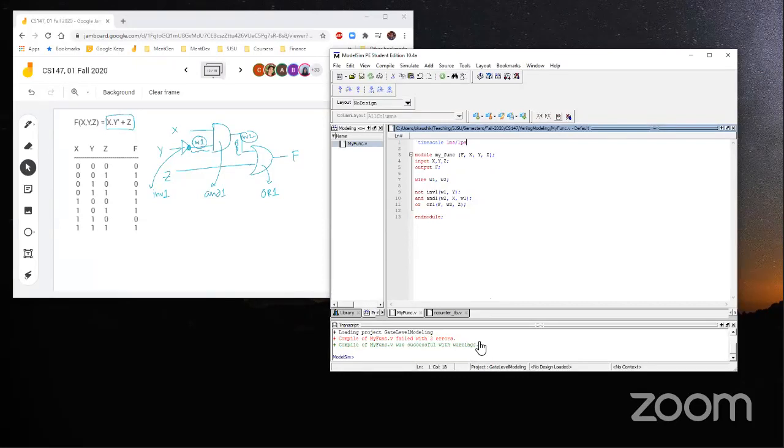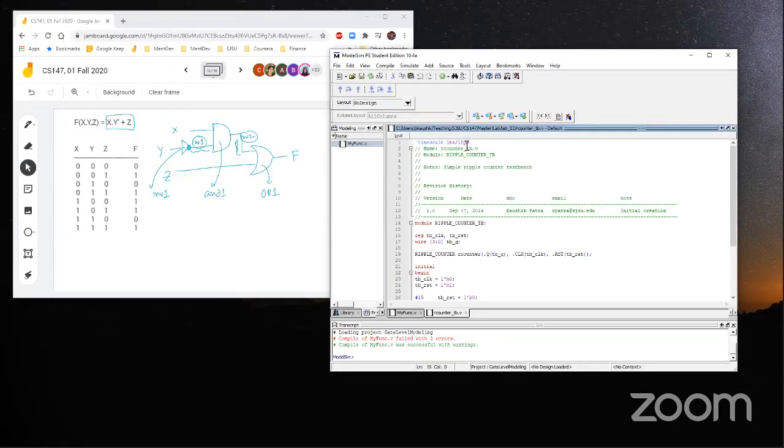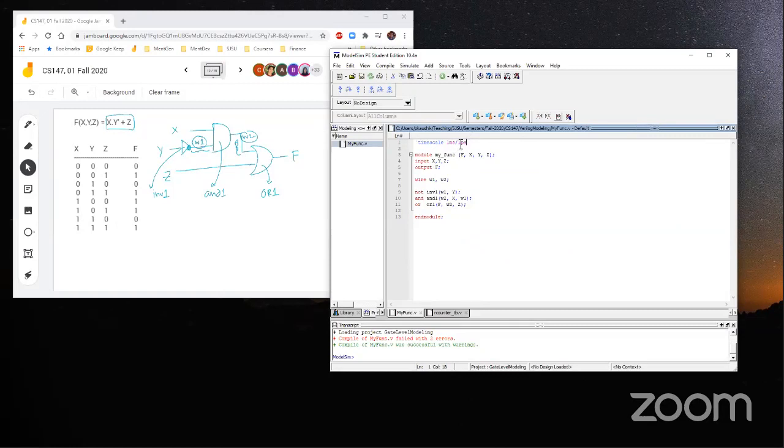This is the precision part. Actually, we can make it 10 picoseconds, which is basically okay for digital simulation. Here we are saying my simulation scale is in nanoseconds with picosecond precision.